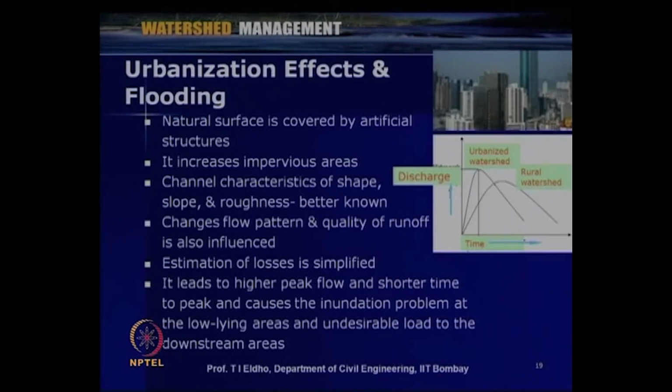So, the main urbanization effects are that the peak of the hydrograph or the discharge will be increased, and the time to peak will be reduced. So, there is a possibility of flooding within a short duration. That is the main effect of urbanization.